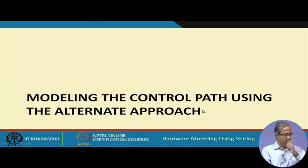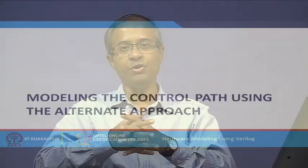Fine. Now, the alternate approach that we were talking about, let us quickly see how our design will look if we use the alternate approach. There is not much difference really. There are two things we have to do. In the earlier case we had defined only one variable that was storing the state vector, but now we will be storing two different state variables. One will be the present state and the other will be the next state.